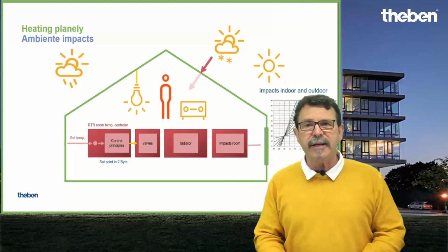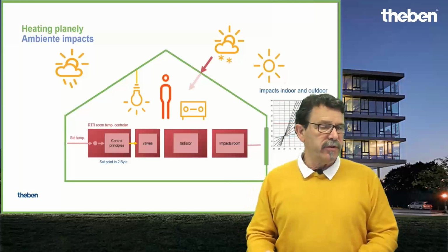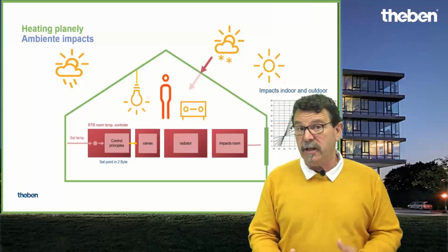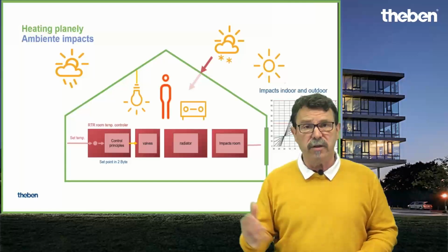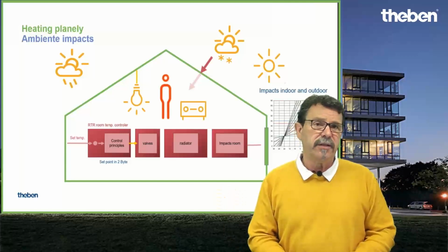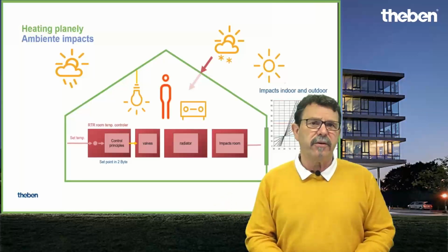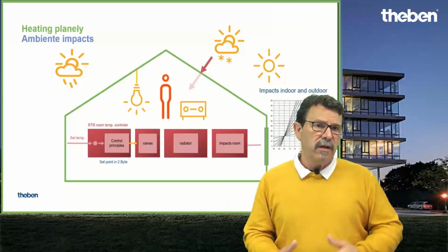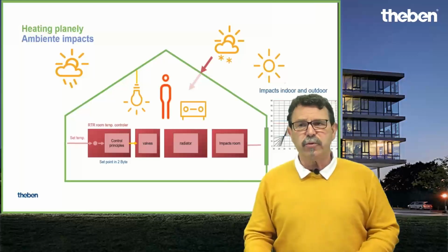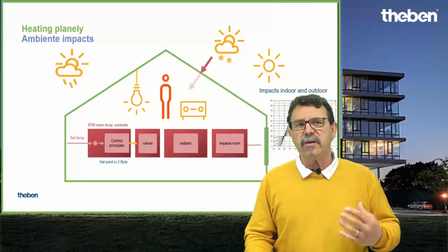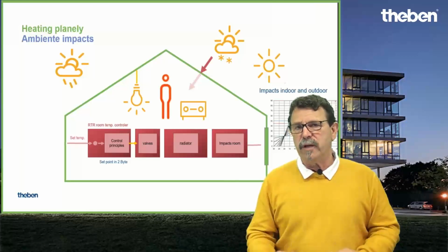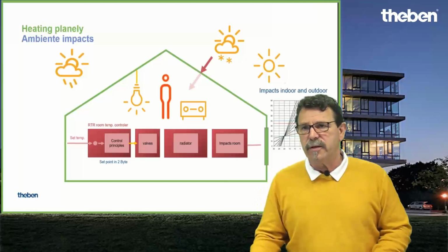This is an office building, so measuring how is the current situation, how is the status, for instance, if there is a window open, yes or no. So if you have a smart RTR, then you can link a window contact directly to the RTR, and the RTR controls comfort mode or frost protection, for instance, during the time when you do a natural airing by opening a window.